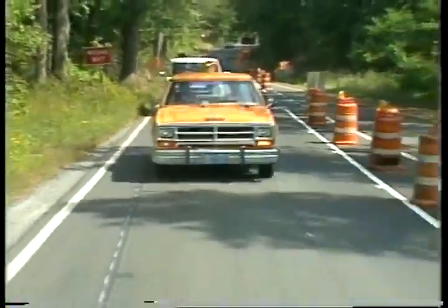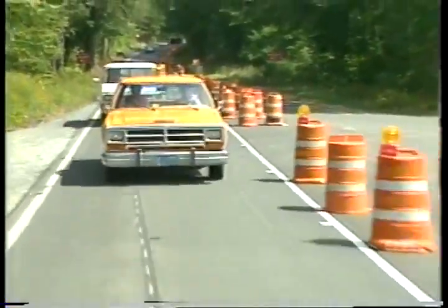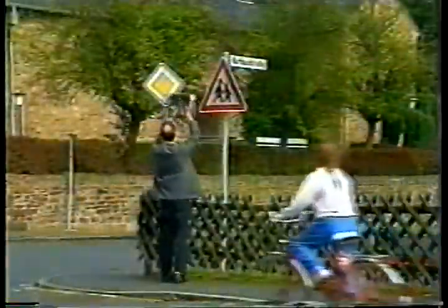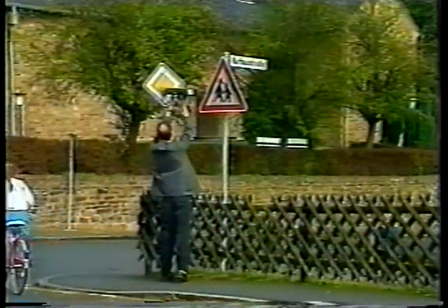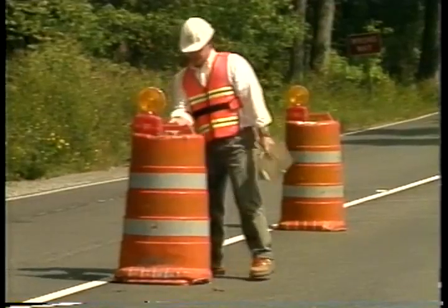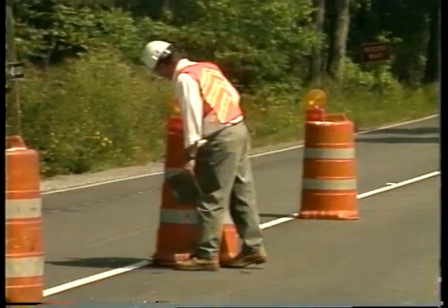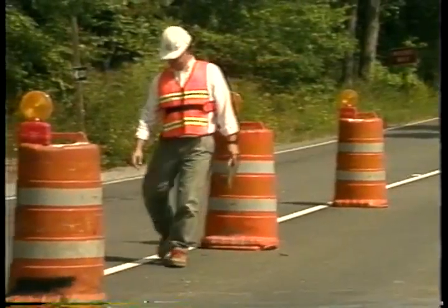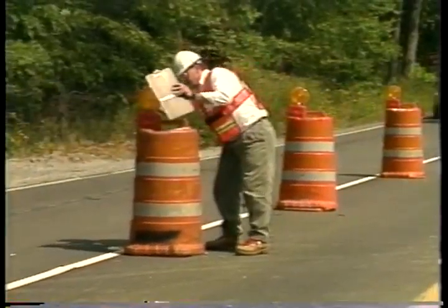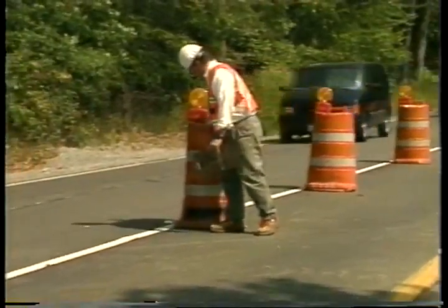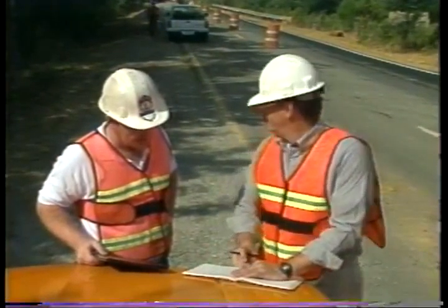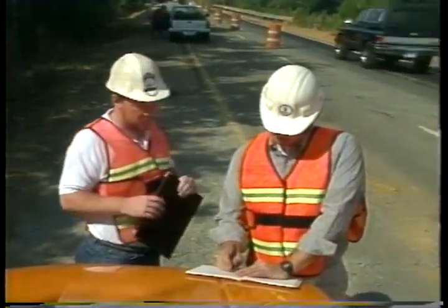Have they faded or become worn and illegible? Are the signs in the proper position? And do they still have adequate retroreflectivity? The engineer should check the same items regarding drums. Then, looking at pavement markings, determine if they are the standard color and if they will be visible at night. Do warning lights conform with standards? Any deficiency should be noted by the type of device and nature of the deficiency.